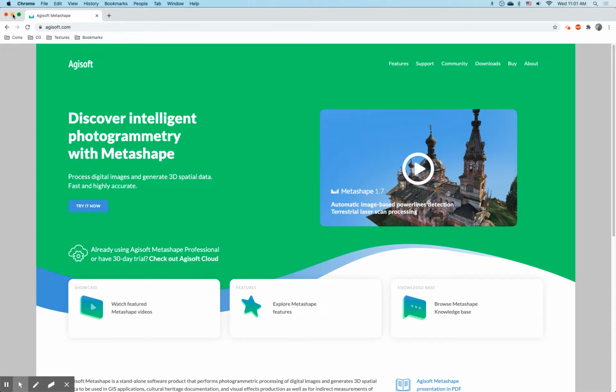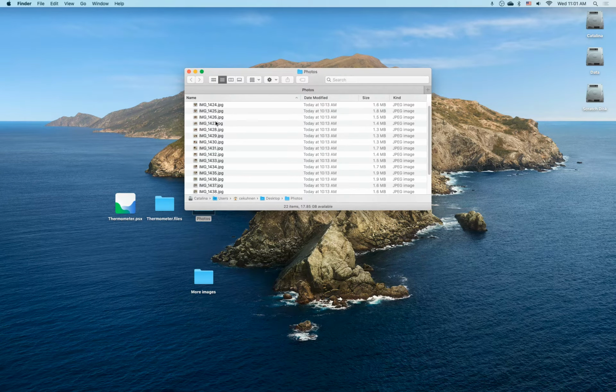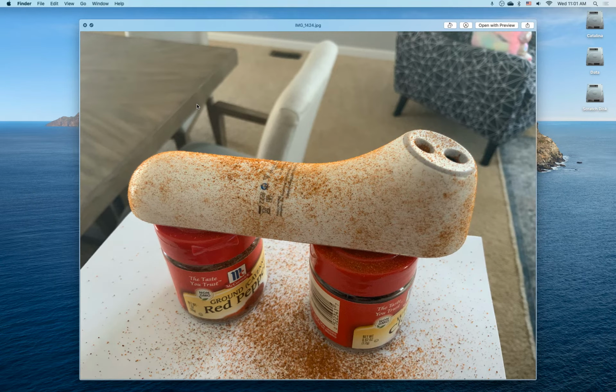So you can download the program for Mac and PC, and I will talk a little bit about how we do the photos, because the photos are really the heart of this whole process. Good photos, good result. Bad photos, bad result. So you might ask yourself, what's going on here? What does photogrammetry not like? It does not like transparent objects. It does not like glossy surfaces. It does not like uniform colored surfaces. It does not like photos where the main subject is out of focus, and it prefers soft illumination, and it does not want to have bright objects or lights in the backdrop.